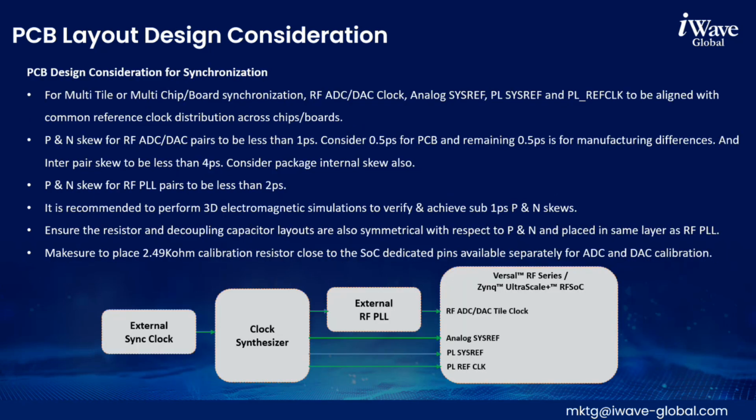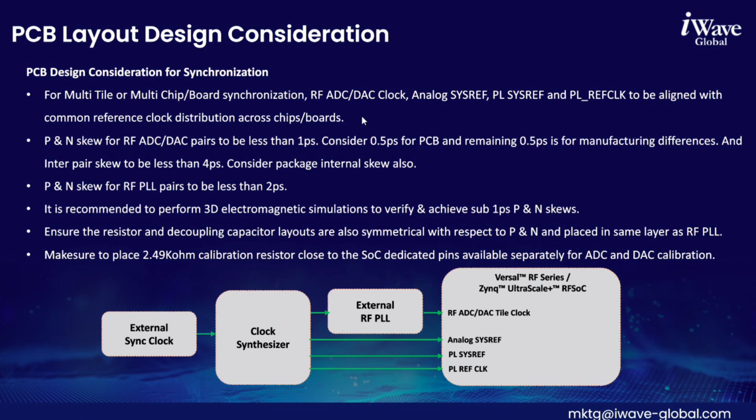So once the power design is done, we also have to take care of the clock design for synchronization. In RF, most applications require the RF channels to be synchronized either within a single chip or across multiple chips, because in beamforming applications multiple channels are coming in and all channels have to be synchronized. So multi-chip and multi-tile synchronization is another critical parameter we need to consider while designing the PCB layout for our RF clocks.